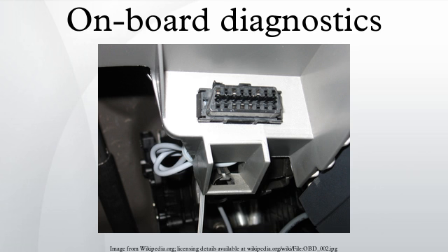The various parameters that are available are addressed by parameter identification numbers, or PIDs, which are defined in J1979. For a list of basic PIDs, their definitions, and the formula to convert raw OBDII output to meaningful diagnostic units, see OBD-II PIDs. Manufacturers are not required to implement all PIDs listed in J1979 and they are allowed to include proprietary PIDs that are not listed.